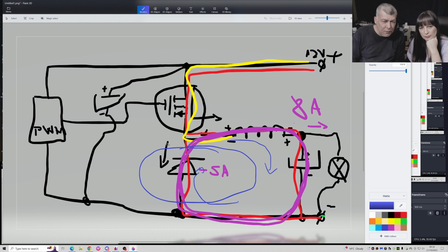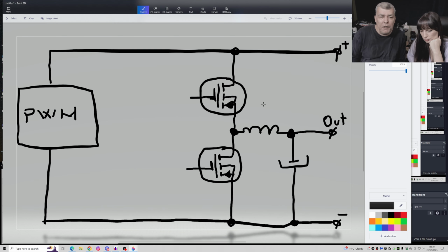What about another MOSFET? When the duty cycle is switching this MOSFET off, we can switch this MOSFET on, and we are closing the circuit. And then when this one is switching off, that one is switching on. Exactly, to charge the coil. What do you think about that? Okay, so basically that's the schematic. We are replacing the diode with a MOSFET.